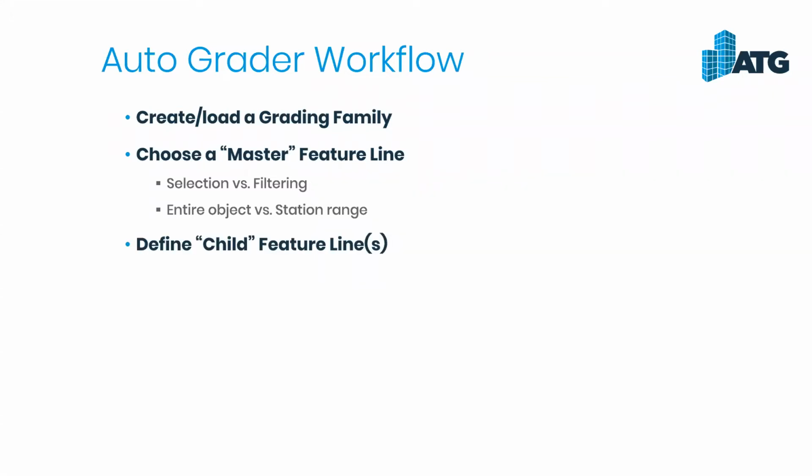After we have that master parent feature line, we're going to define all of the other child feature lines that are going to be based off of all of that. Again, what we're doing here is we're just adding various elements that are going to ask us, how do we want to solve this right triangle or series of right triangles? And it is important that we have a couple of different options for choosing our attachment point, direction, left, right, inside, outside, so on and so forth.